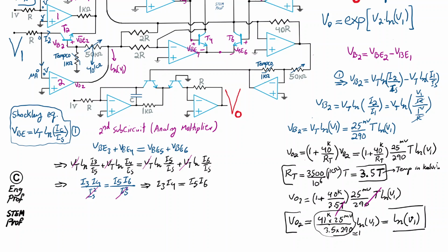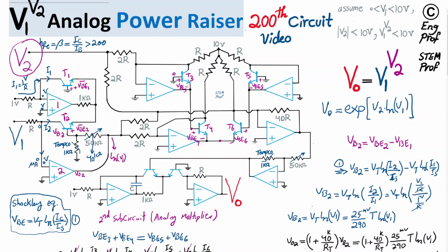Now the job is just substituting these transistor currents. So I3 is just the sum of two currents. There is no current going through the input terminal of the ideal op-amp because it has infinite impedance, and then the virtual ground, let's say the virtual short, will be present. So as a result, we have 0 volt for the positive terminal, so the negative terminal is also 0 volt. Same idea, across this resistor 2R we have a V2 voltage. So the current that is coming this way is V2 divided by 2R.